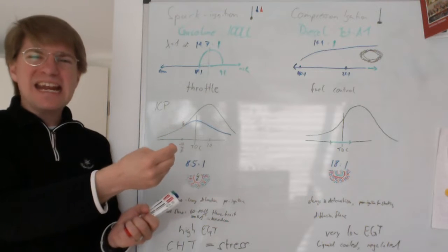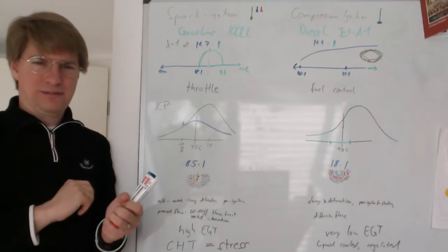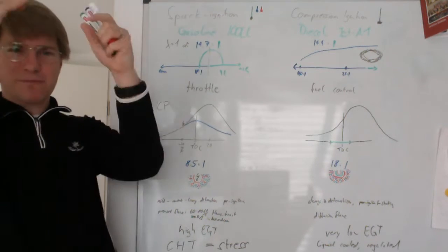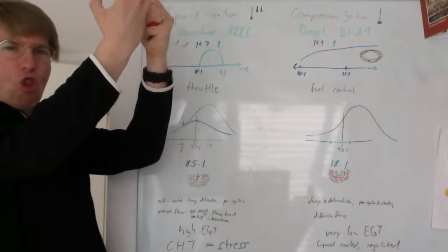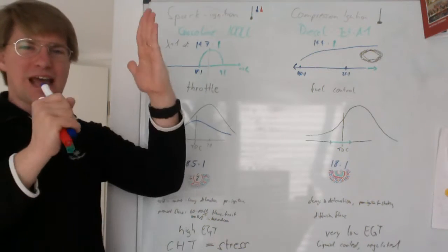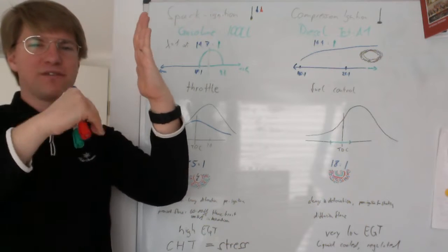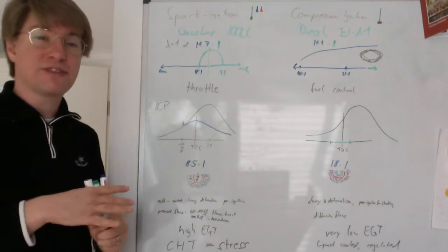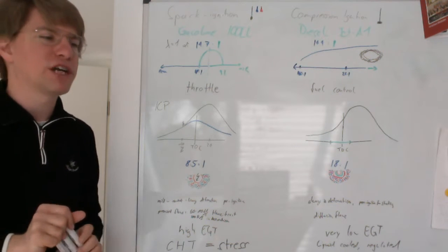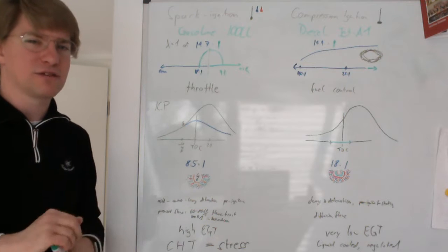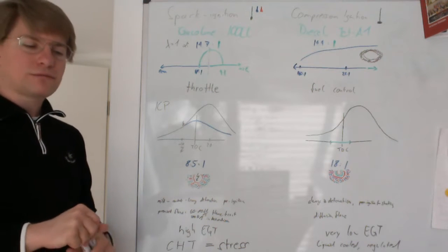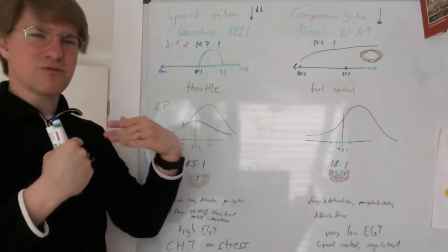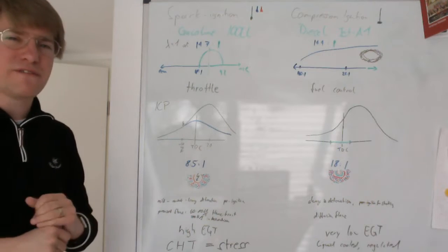So when you run at anything less than full throttle, you're literally throttling the engine. What happens is the piston moves down with the intake valve open. It's trying to suck in the air, but it has to work against the partially closed butterfly valve. That creates a vacuum behind the butterfly valve. That's what you see on the manifold pressure gauge. It's less than ambient, it's less than 29.9 when you are at a partial throttle. And of course, this sucking against the resistance of the throttle valve lowers the efficiency of the engine.